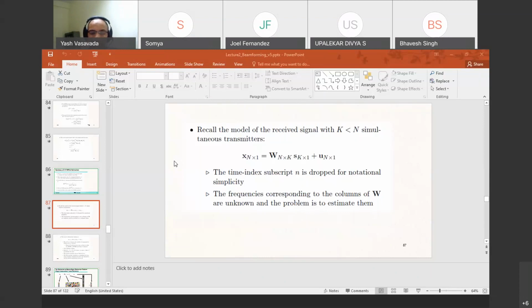And if you are at the actual incoming signal frequency, then all of those dot products are going to become zero. And so the way the MUSIC algorithm formulates the scheme is it puts that dot product in the denominator. Therefore, when you get zero as the dot product, the ratio is going to become infinity.